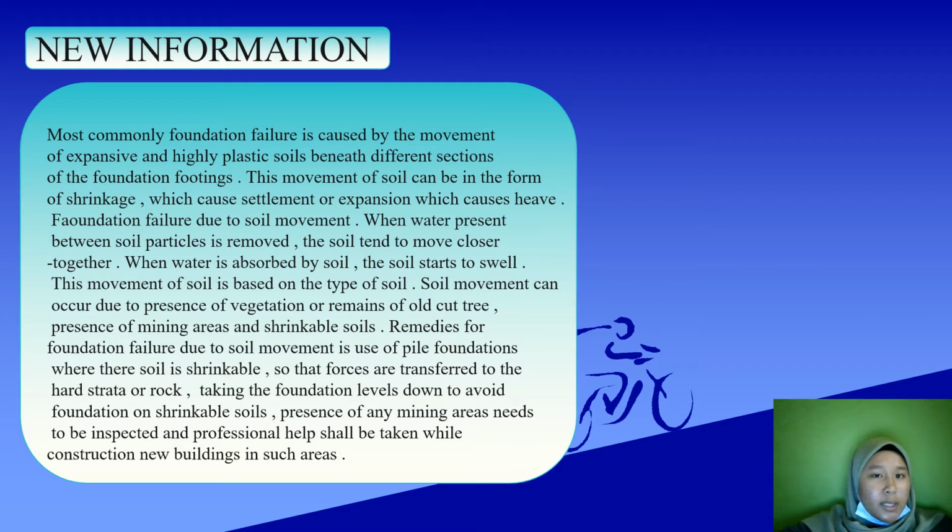New information highlighted in this report is that the most common foundation failure is caused by the movement of expansive and highly plastic soil beneath different sections of the foundation footing. This movement of soil can be in the form of shrinkage, which causes settlement, or expansion, which causes heave. Foundation failure due to soil movement.